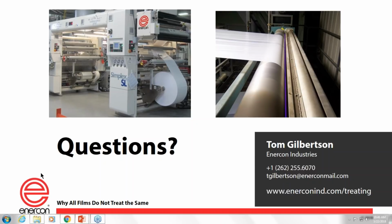Does the length that a corona treatment effect lasts depend on each individual material? It depends on how long the treatment lasts, the decay rate. If I can rephrase that question, if he's asking whether the dyne level decay rate changes with the type of material, the answer to that is yes.